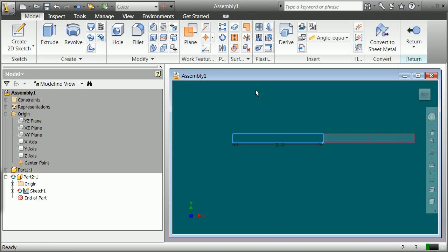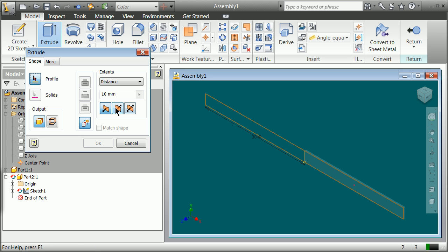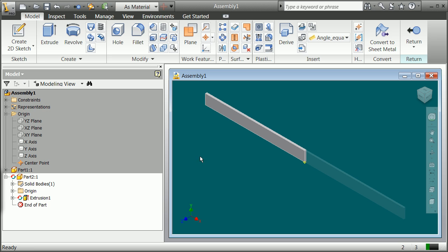You see there, I can hit F6. And these aren't lines that I'm going to use in the end, so now I'm going to extrude once again going in, this time 2 inches. Grab my profile, push in, hit OK. Now I've got both of those parts done.